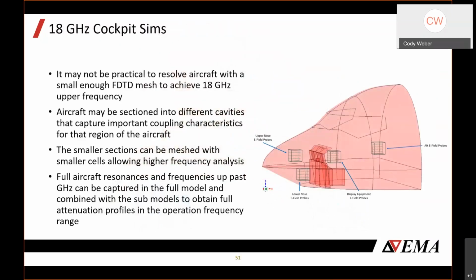And so finally, one of the things that always gets brought up is some of the higher frequency applications. And so it's quite easy to understand for the cable response to a HIRF environment how your simulation model can resolve those details. And that up to 400 megahertz, it's very doable within our finite difference simulation approach. Of course, there are other techniques for going to higher frequencies, and they certainly have merit and value in using that, but that's not the approach that we use at EMA.